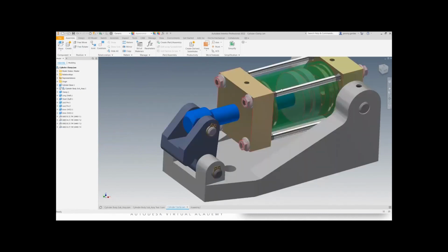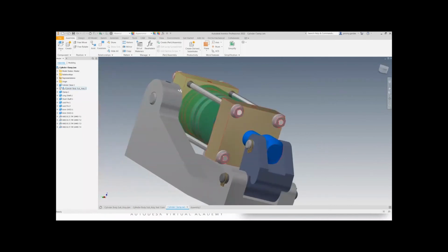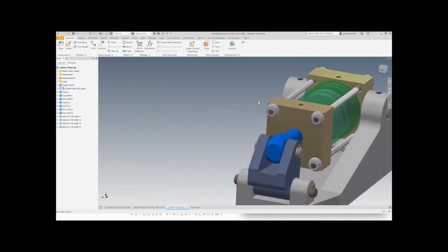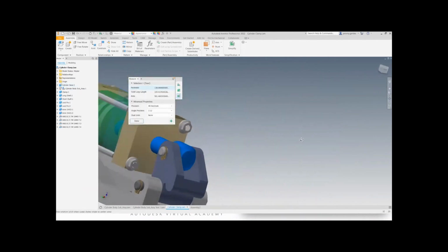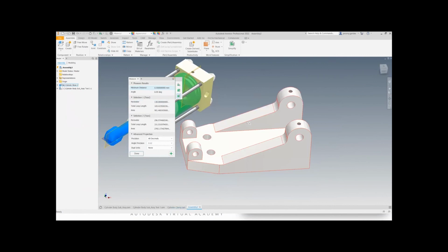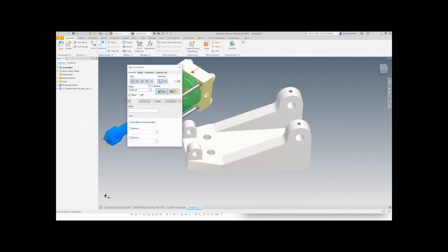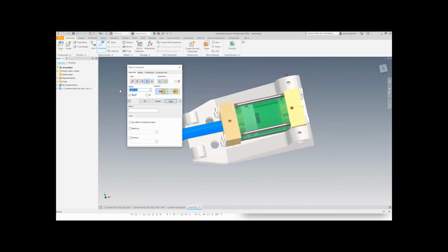Okay. And let's measure, because looking at this, since I know that it's going to be aligned with these mounting holes back here, that's how I would start with my constraints. So I want to measure from this face to this face, and it's 0.5 millimeters. So if I start a constraint, go to insert, select there, and then I said 0.5. All right.